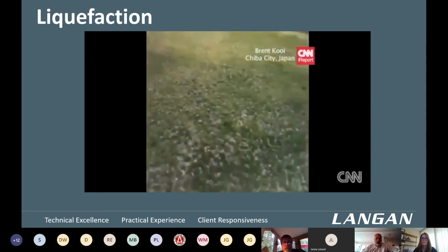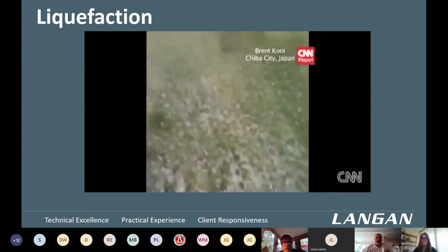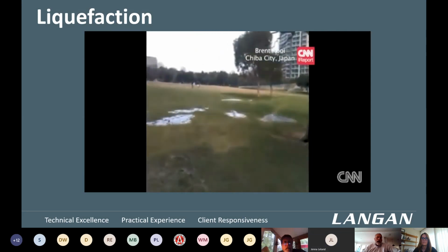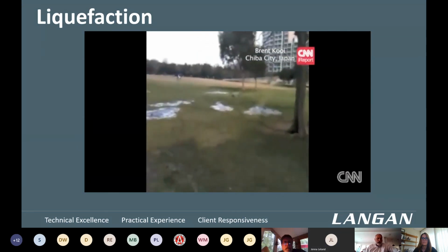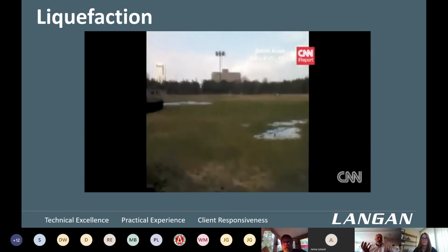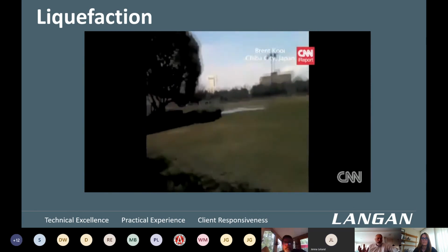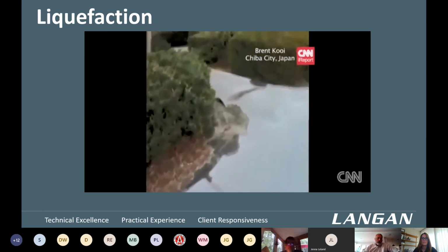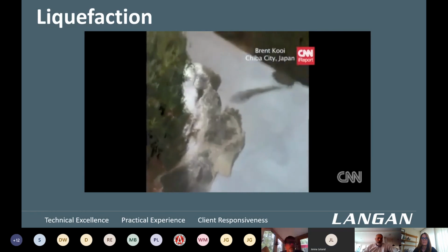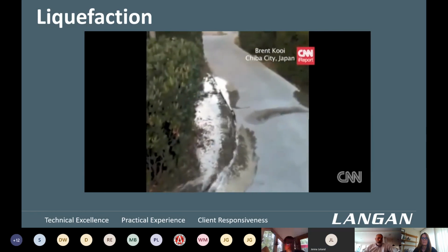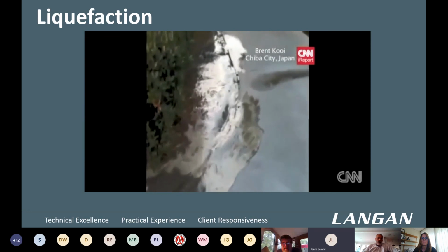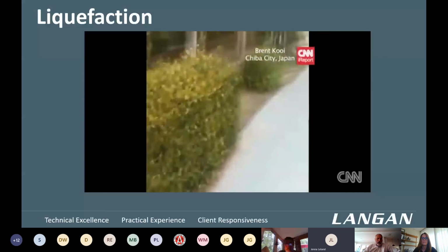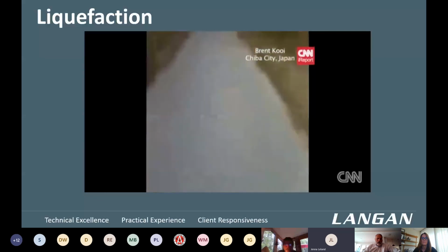For now, it looks okay, but as you can see, now this is liquefaction in action. The soil has liquefied, and you get this ejecta, which is basically a reverse gradient, because there are higher pressures lower in the ground, and with the water, it liquefies the soil and brings it up. And you can see it here as well. On the edge here, the ground has liquefied and continues to liquefy. It brings up soil with it, basically is saturated. Loose sand is the worst kind of condition that you can have when earthquakes happen.